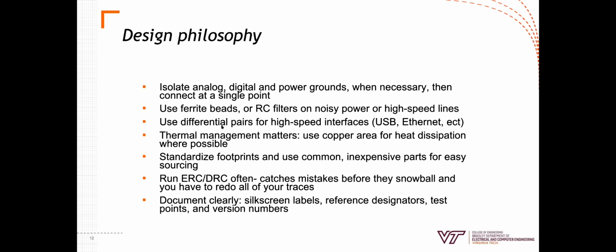Differential pairs are impedance matched traces for high-speed interfaces. For USB, you'd use a differential pair, and this matches the impedance so that the signal is as high quality as possible when it gets to the chip that takes in the USB. This makes sure that they're at the same level and one isn't more attenuated than the other for when they use a comparator against them.